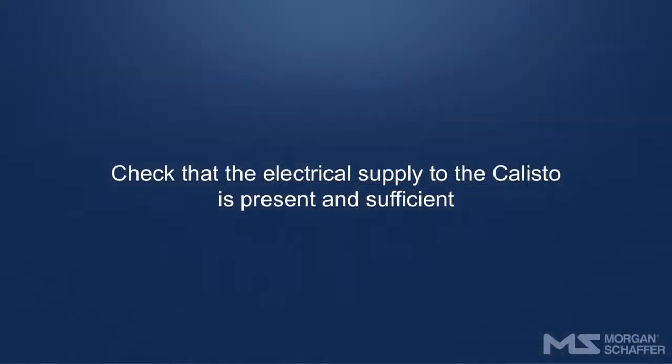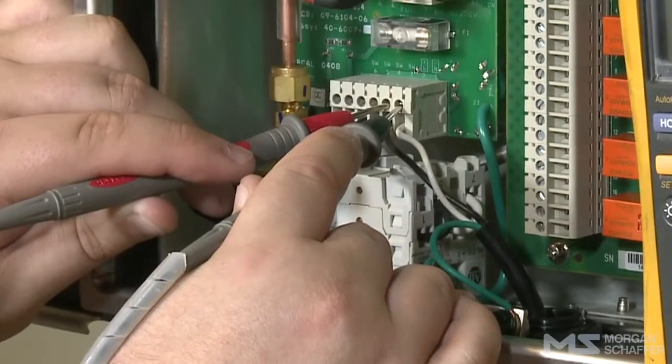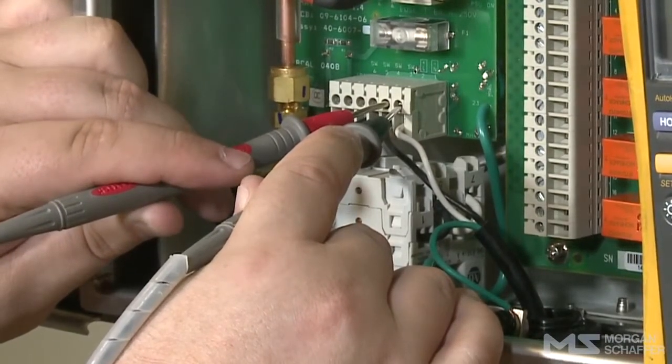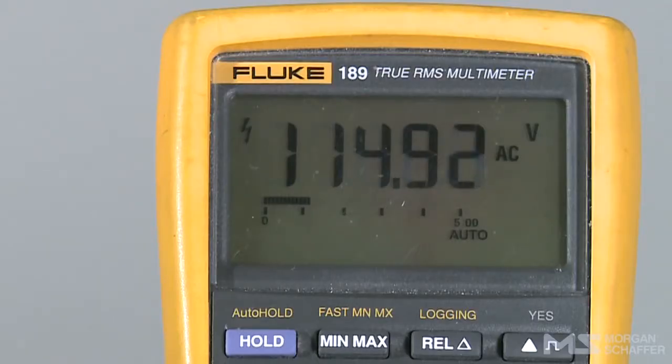Check that the electrical supply to the Calisto is present and sufficient. Connect a multimeter between pins 1, L positive, and 2, N negative, of the main I/O's TB1 connector. The voltage must be between 100 and 240 volts alternating current, or 100 and 220 volts direct current. If this is not the case, ensure that the Calisto is supplied by a power source between 100 and 240 volts alternating current, or 100 and 220 volts direct current.